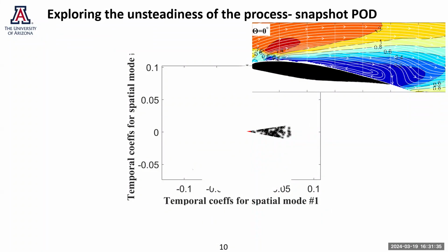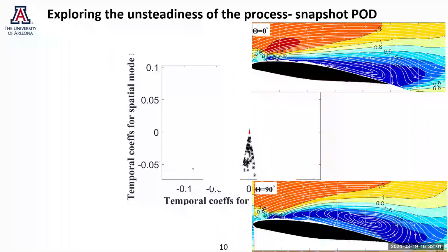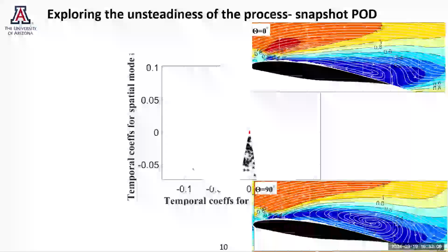If you look at this particular wedge of the data, at theta equals 0 we have a relatively thinner recirculating region, and a flow acceleration, which was not there for the ensemble average results. Now, if we look at another sliver of the data, we get the phase progression, wherein we have the enlargement of this recirculating region.